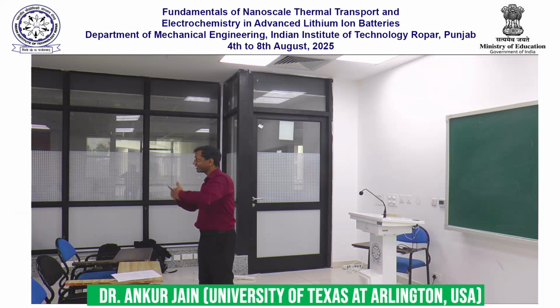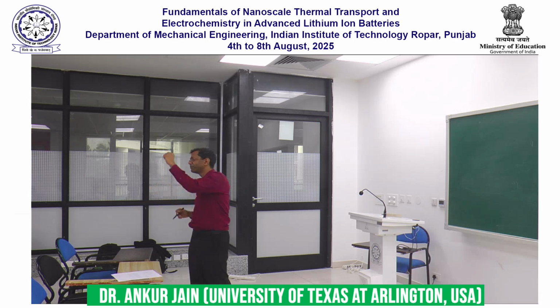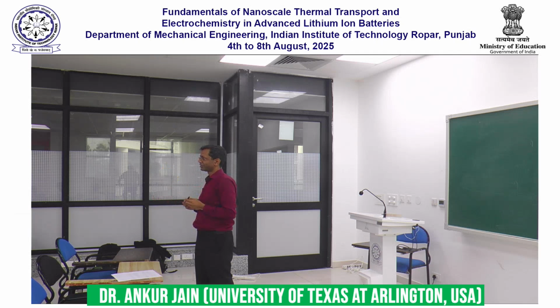This body will generate heat. If you wait long enough, all that heat will go into the water surrounding it, because of which the temperature of the water will rise, right? Then if you can go and measure the temperature of the water before and after your experiment, you can from there say mCp delta T is the amount of heat that must have been generated by this body, right?